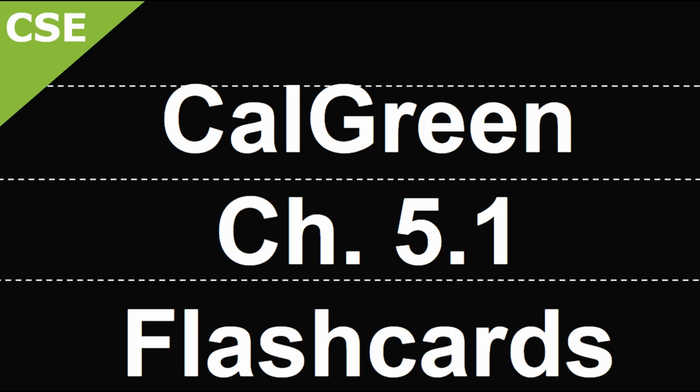There are many combinations for compliance, whatever the example, but let's practice a simple one together. If 55 total actual parking spaces are provided in a new building project, CalGreen table says you need 13 EV-capable spaces, with 3 of those as electric vehicle charging stations, which means equipped with EVSE and ready to charge.